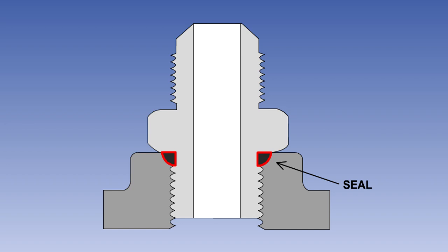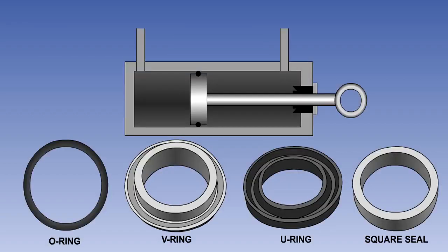Seals perform a very important function in a hydraulic system, their primary purpose being to prevent leakage of fluid. Static seals, gaskets and packing are used in many locations, and these prevent fluid leaks by being squeezed between two non-moving surfaces. Dynamic seals, fitted between sliding surfaces, may be of many different shapes, depending on their use and on the fluid pressures involved.